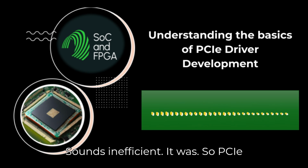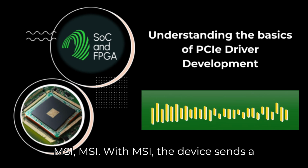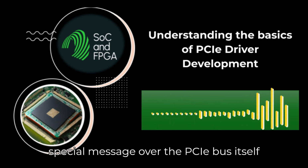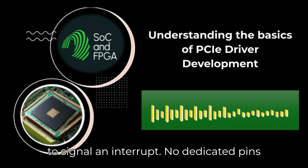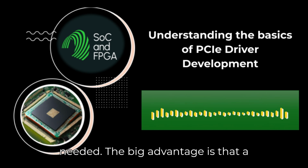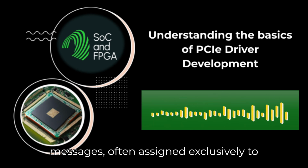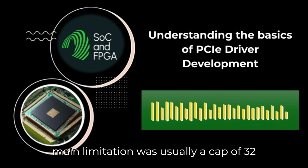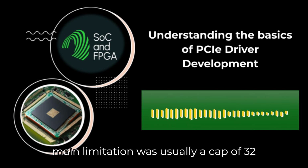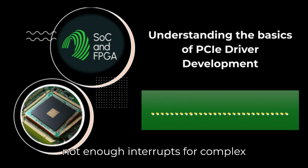It was. So PCIe introduced Message Signaled Interrupts, MSI. With MSI, the device sends a special message over the PCIe bus itself to signal an interrupt. No dedicated pins needed. The big advantage is that a device can have multiple distinct MSI messages, often assigned exclusively to it. This gets rid of the sharing and polling problem, reducing latency. The main limitation was usually a cap of 32 interrupts. So MSI was better, but maybe not enough interrupts for complex devices.